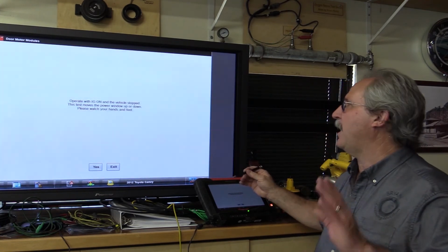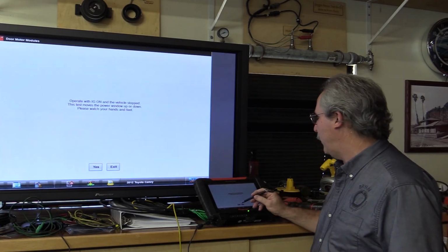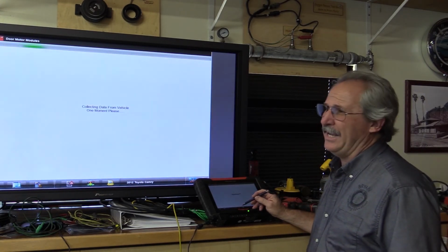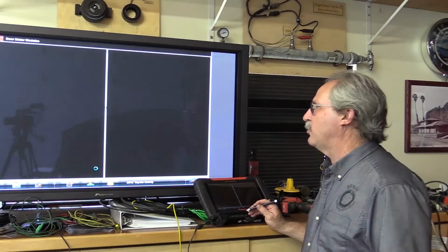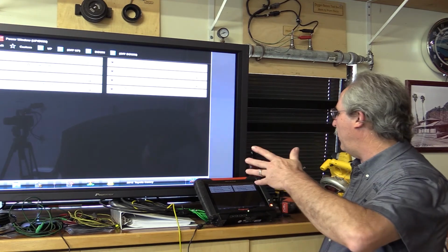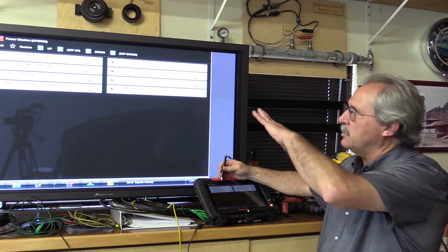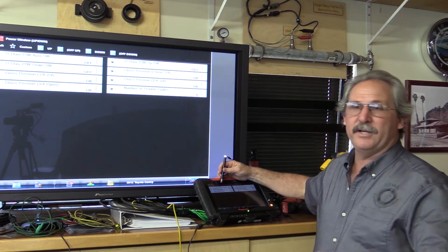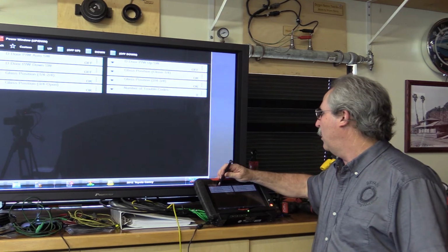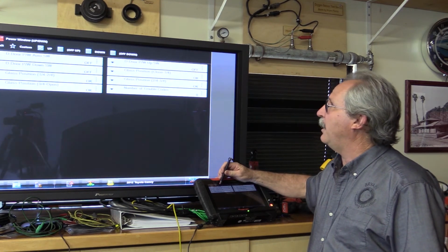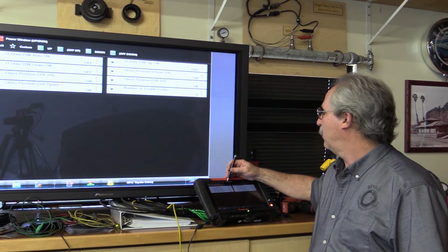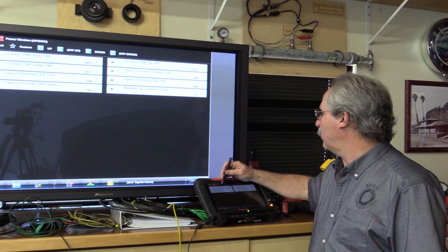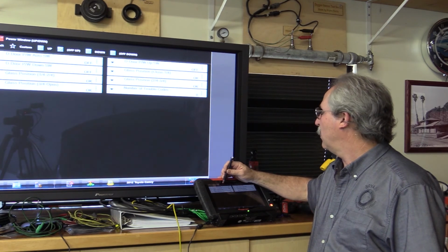Now I can use the scan tool to make the window go up and down. It tells me to wash my hands and my feet for some reason. I'm not sure why my feet are going to be in the window, but better safe than sorry. So now I have these functions, the same PIDs we just looked at, but now instead of having someone get in the car, I can put it up. I can also put it down. So I can work the window up and down.